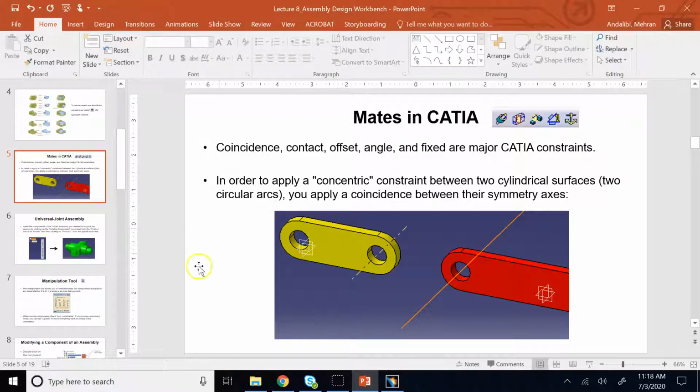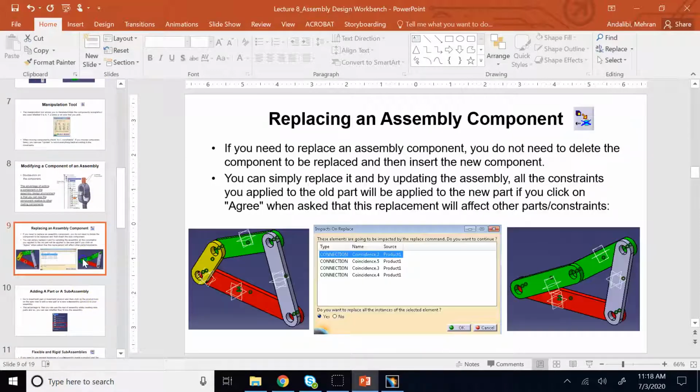What I want is to create this mechanism called the 4-bar linkage, which is 4 links connected together. One of them we fix to be like the ground, and the 3 others are free to move. One of them is the input link, the other one is the output link, and the green one is the connector link. You might wonder, where would you see such a thing in real life? Where would you see this mechanism, which has 1 degree of freedom overall?